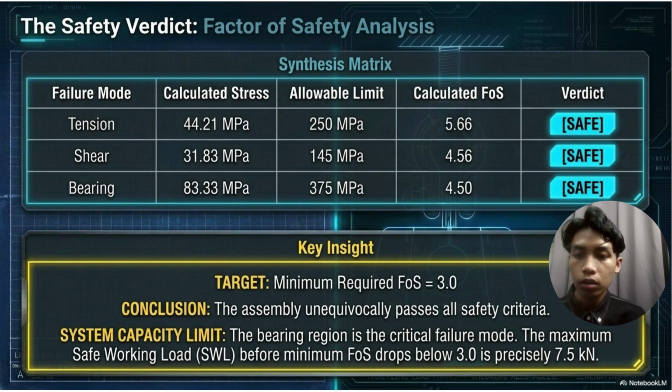Next is shear. We recorded a calculated stress of 31.83 megapascal, and the allowable limit at 145 megapascal, resulting in a factor of safety of 4.56.